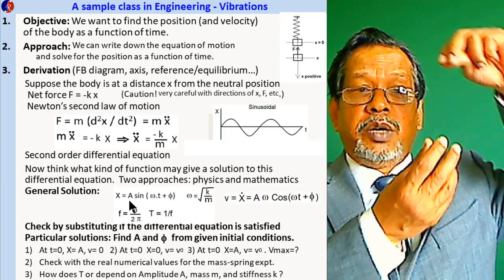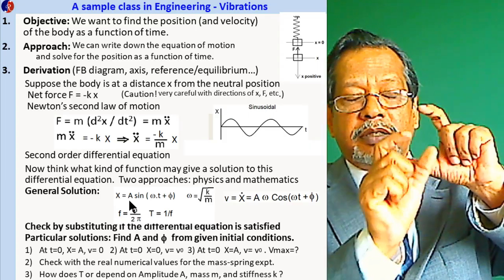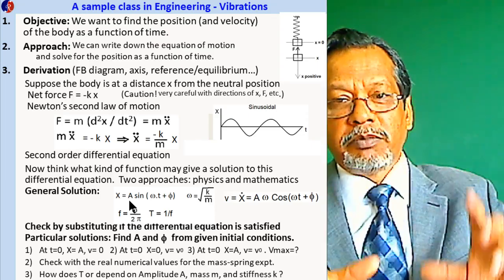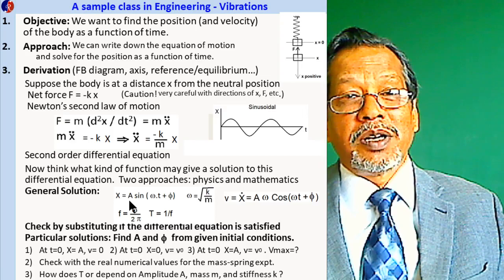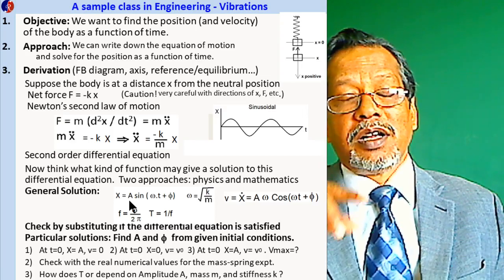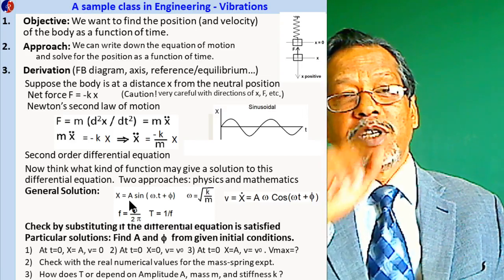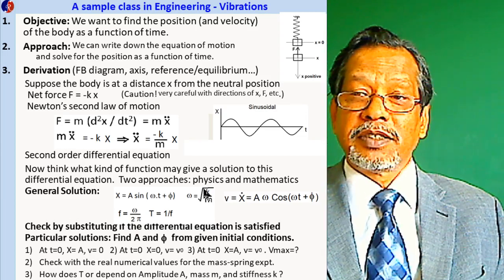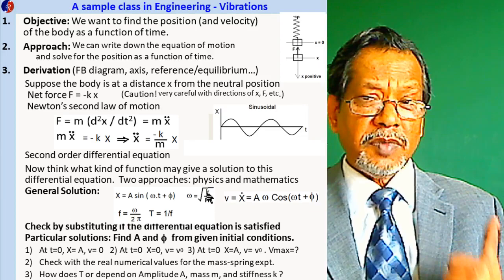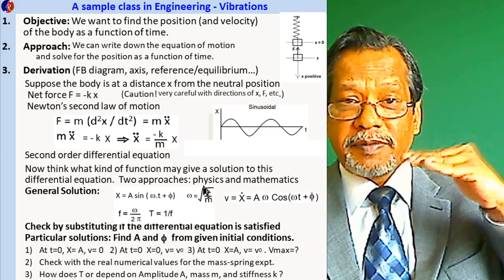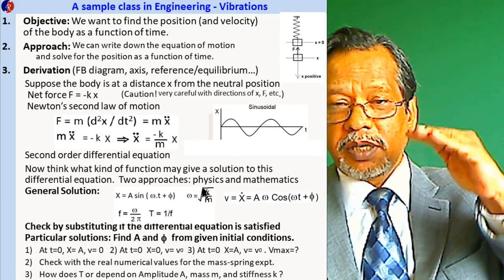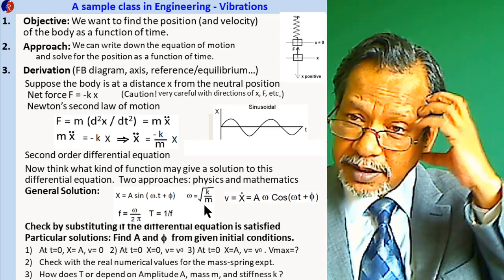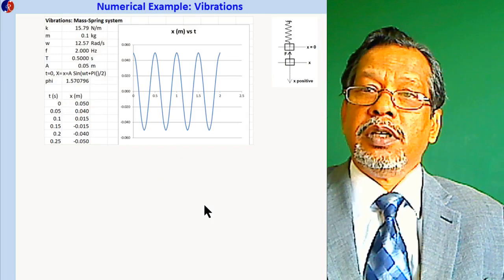Do that experiment right away: measure the timing with video, stretch it even more and do the same thing. You'll be surprised that it doesn't depend. The time period, how much time it takes to complete one cycle, doesn't depend on the amplitude. It depends only on mass and stiffness. If it's stiffer, it vibrates faster. If it's a softer spring, it vibrates slower. Heavy mass, slower. The denominator is something they should get by thinking.